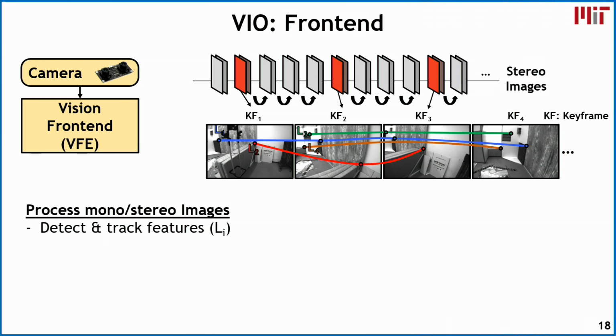These 3D landmarks in the environment appear as 2D features in these actual images, and we want to track them across the different frames or across time. And by tracking these particular features, it gives us a sense of which direction and where the drone is actually looking. So for example, if you follow the red line here showing landmark number 2, you can see that its position within the different frames will vary, and you can get an idea of where the robot is actually moving